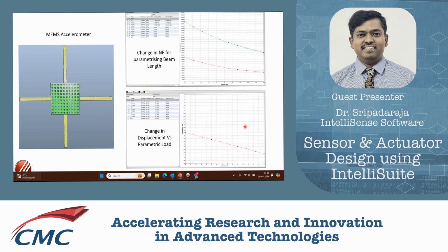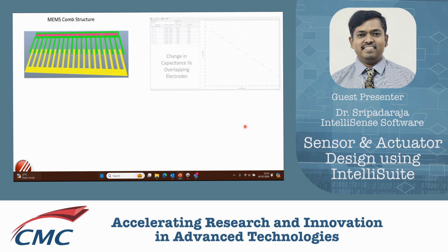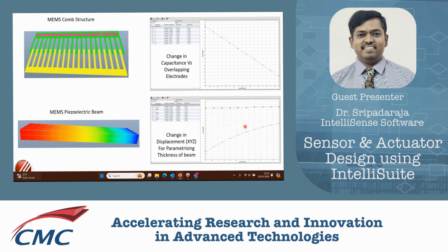So it does the simulation, which generates a lot of models and repeats the simulation on all of the models, and then throws an output which helps to have better clarity on how the device responds and helps in freezing our device dimensions as early as possible. The same similar case applies for a comb structure or a capacitive type of device and a piezoelectric beam as well.